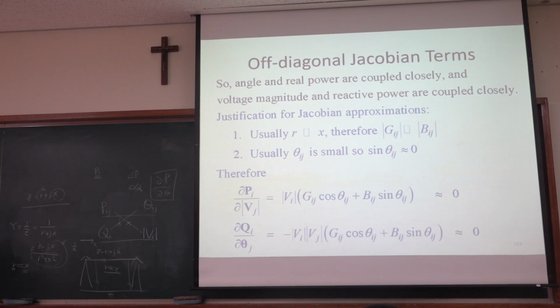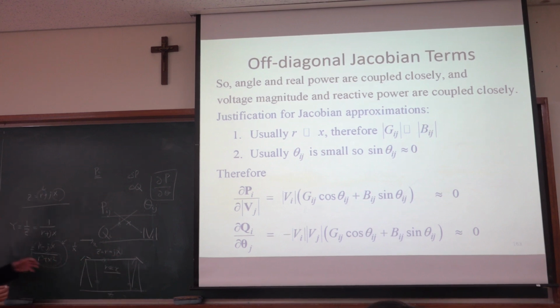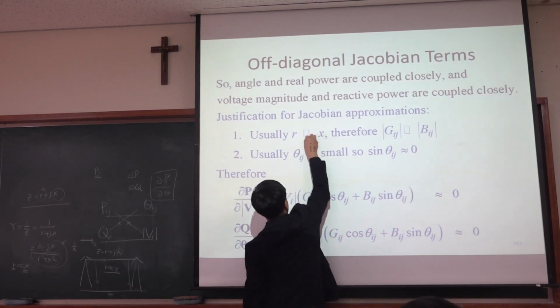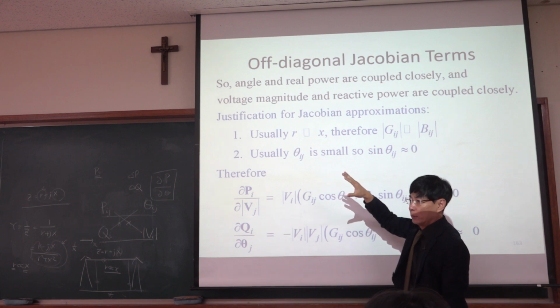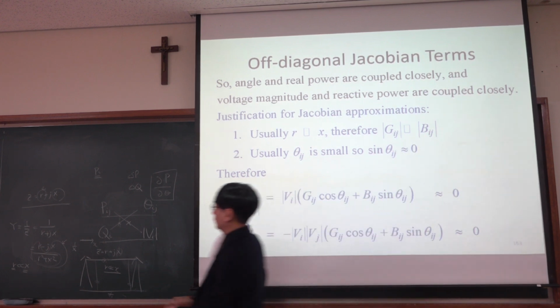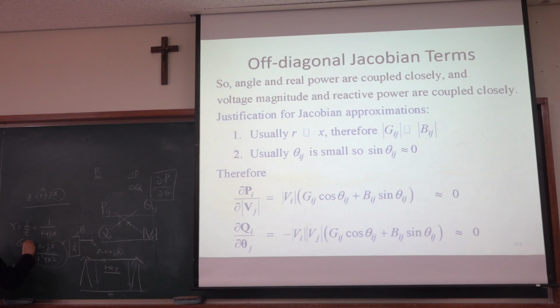Okay, so when this inductance component or reactance component is high, our admittance becomes smaller. Okay. Am I saying correctly? Yeah. And so usually, we have this relationship. So this G conductance is 0, can be assumed to be 0. So this B is dominant. Okay. Similarly, we only have this part. So this is a B part, right? This is G part, and this is almost 0.